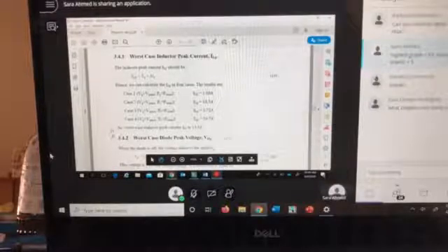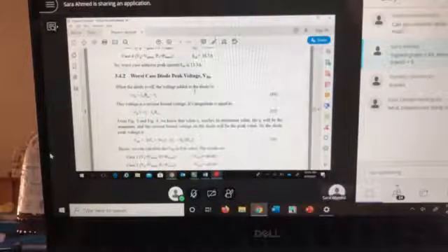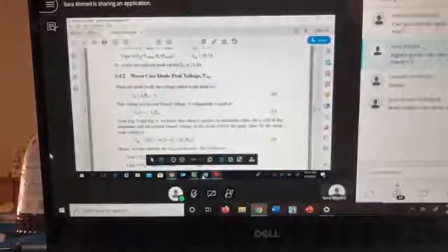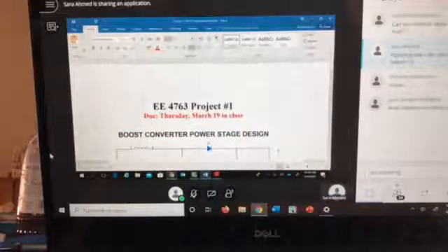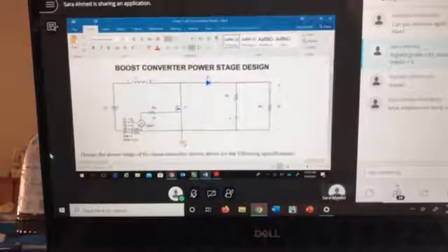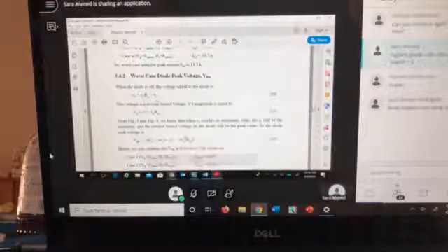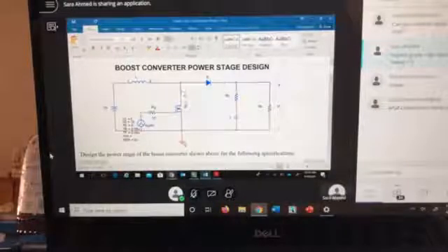Okay, so after that, what do you have here? We asked for the diode peak voltage. So where's VD? How do we get VD? Let's go here to the schematic and think about the voltage across the diode. The equation here tells us VD will be equal to the drop on this MOSFET and V out minus V out. How do we get this? Just a KVL equation. In this KVL equation, you basically have the voltage across the MOSFET, which is just your R on times I.